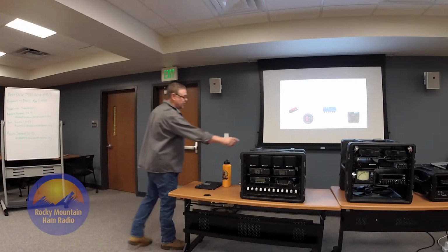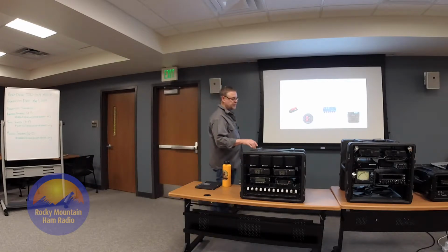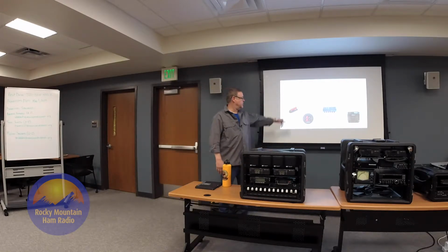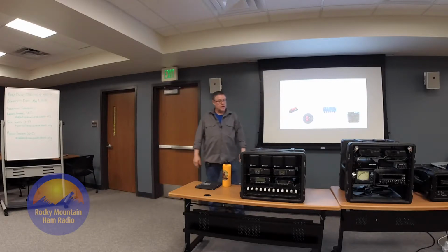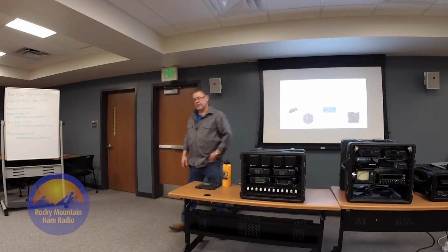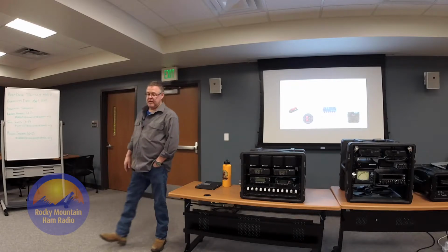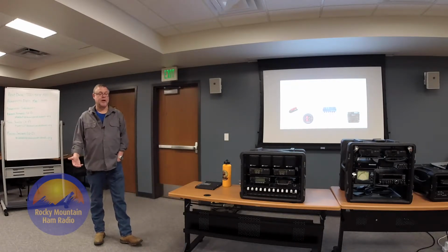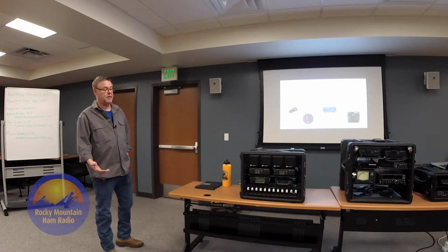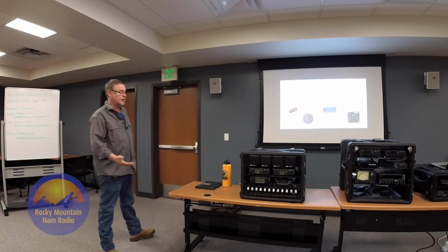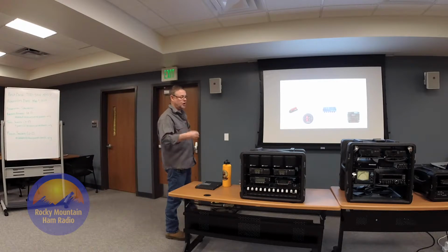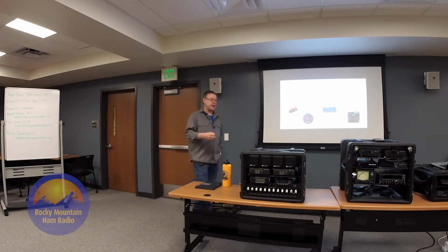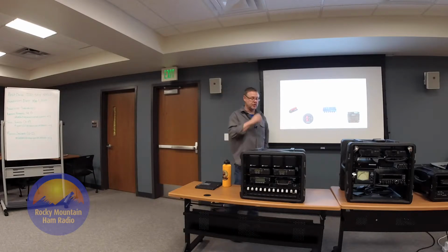This was originally built with terminal strips. It's now got rig runners in it and one of those. But that's a cheaper way of doing it. It's sturdy, it's mechanically sound, it works great, takes up a lot less space, and they don't weigh anything. And it's easy to crimp on the little spade connectors and the eyelet connectors onto the back of your wires when you're making your interconnection cables.